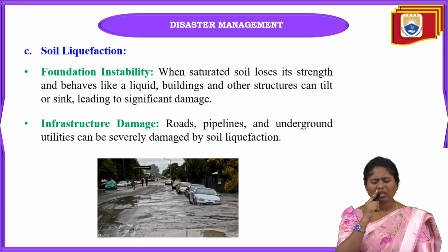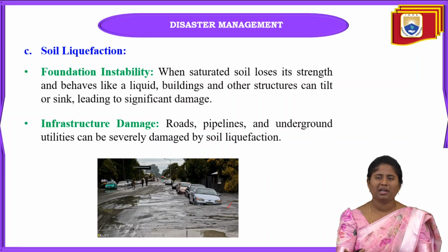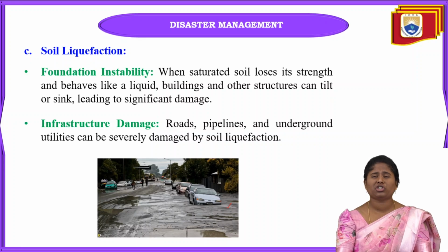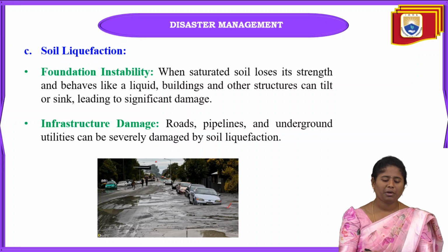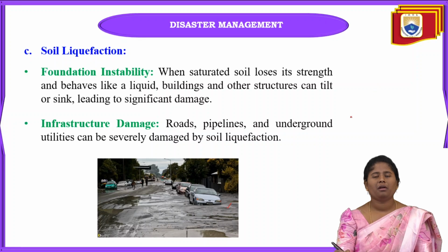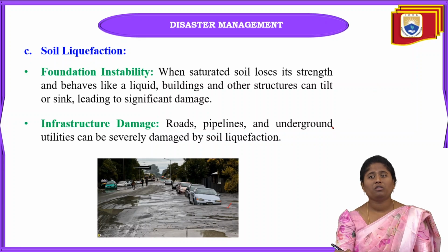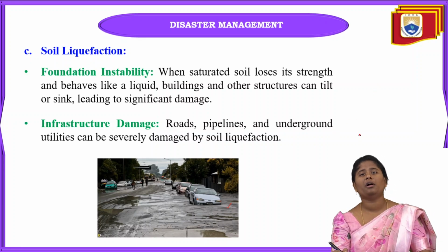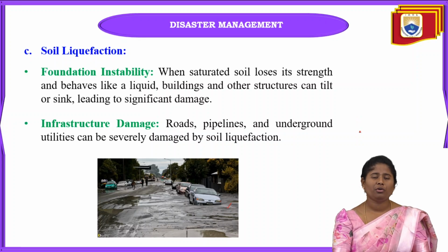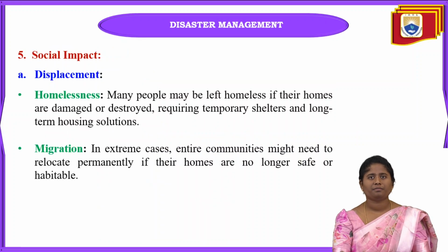That's why there will be so much damage to buildings and other structures. Why? Because of the liquid form, they may tilt or sink. This foundation instability gives very much damage to the overall infrastructure projects also. Next one is infrastructure damage. In this one, roads, pipelines and also underground utilities can be damaged due to this soil liquefaction.